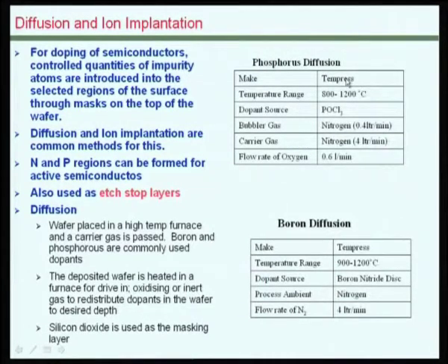There are different options available, and you typically have nitrogen gas as the atmosphere. The dopant by itself is coming from a compound of phosphorus or boron, which is essentially the source of the respective materials.